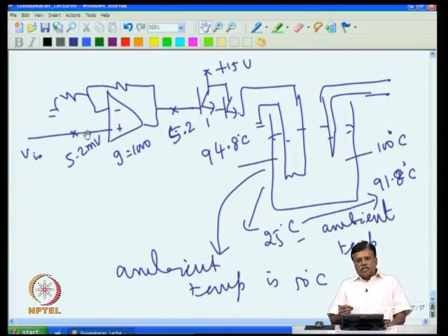If the temperature has to be constant throughout the day, then the only choice is to increase the gain, don't keep a low gain, go for a high gain. But high gain will make the temperature go up and down. If you keep it at low gain, then from morning to evening, if you watch the temperature of this, it will be changing slowly. So this is a serious problem, and this was recognized first by the practicing engineers in the industry.